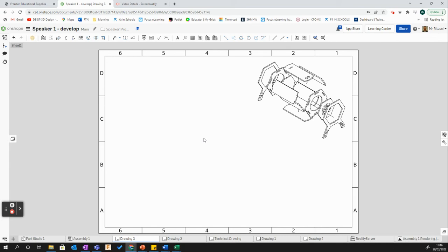And then what's also nice about this feature is this button up here called callout. We can click that and we can number the parts. To do that, all you have to do is delete this little thing here and type in number 1. Okay, and that gives you number 1. So I'm going to number this part number 1. Let's put this next here. Okay, then I want to do number 2. So I'm going to press delete, press 2.